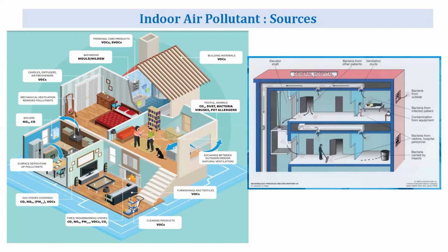Once you are maintaining the temperature at somewhere around 25 degrees, this particular pollutant tends to sustain. So this is just to give you a feel when you are planning an HVAC system or any intake system. Please remember, if the building is near the road and you have an intake here, then you are just extracting the pollutant from the road and putting it inside the building.